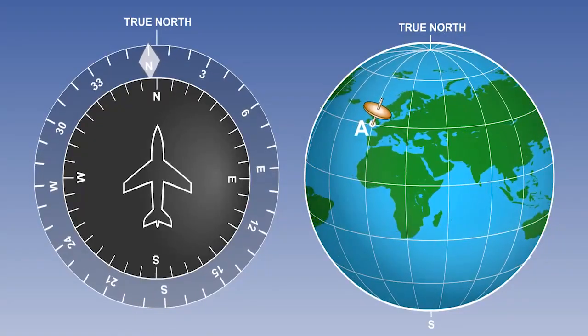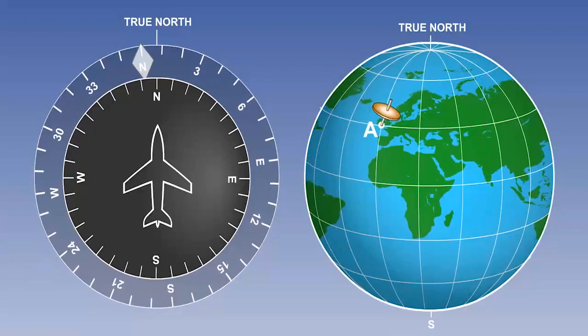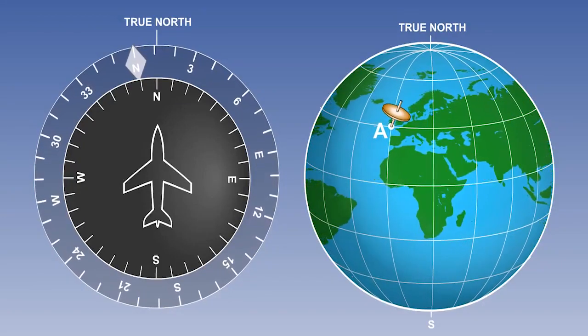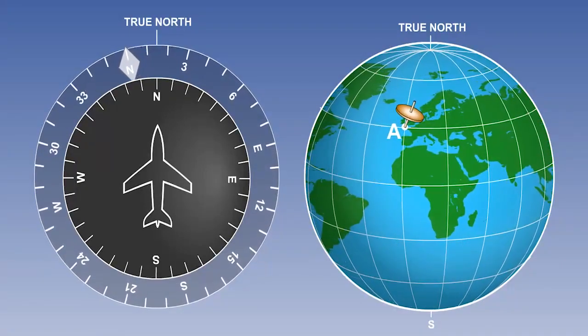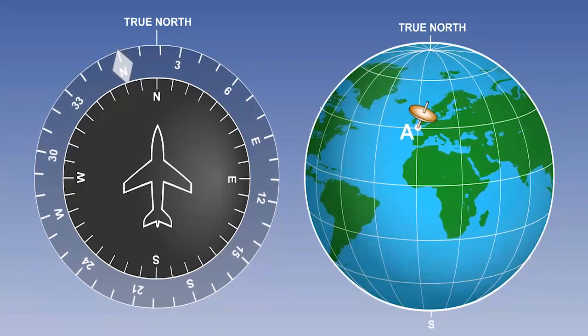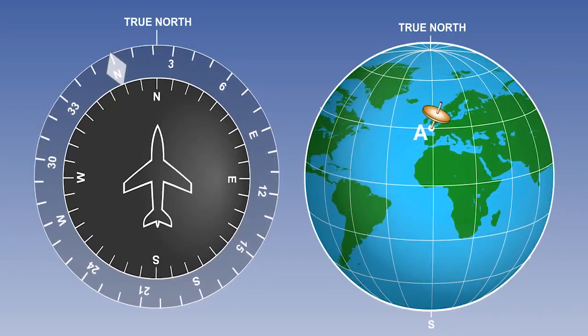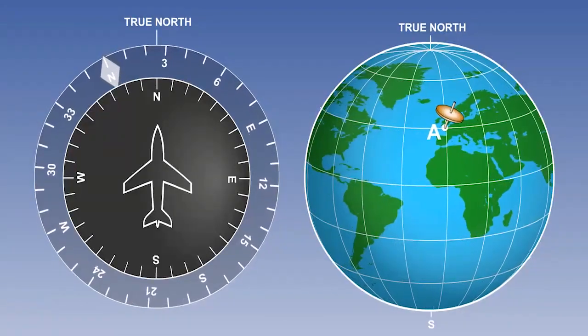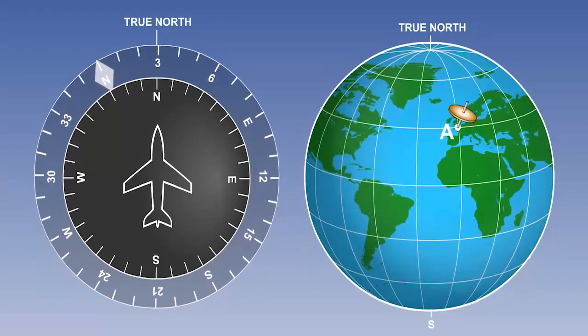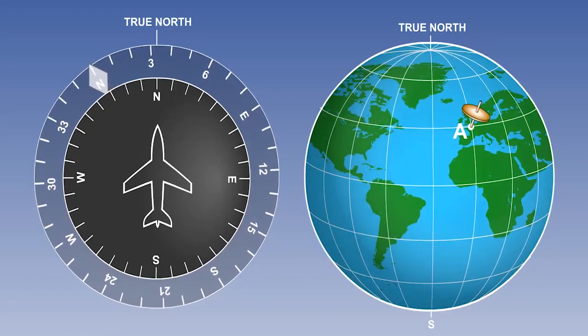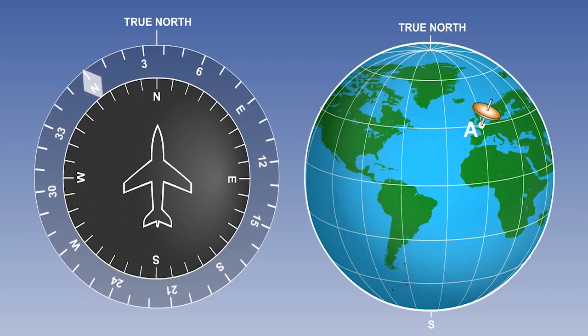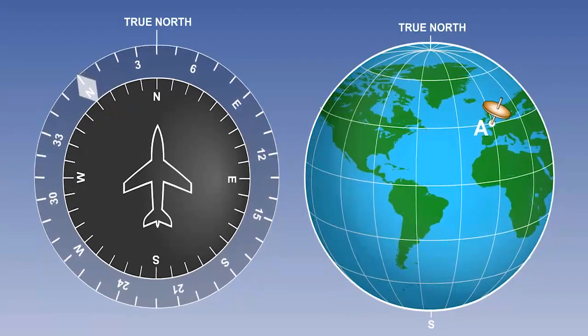Earth rate occurs because the gyro is aligned with true north at some particular meridian. The aircraft then rotates with the Earth along with the meridian, but the gyro continues to remain in alignment with the point in space where it was originally aligned. The correction factor is 15 times the sine of the latitude in degrees per hour.